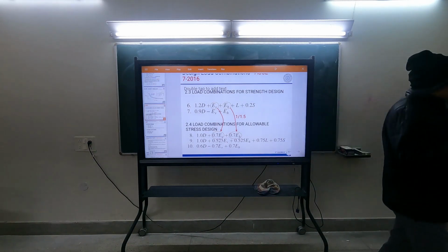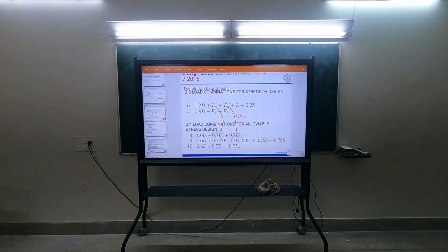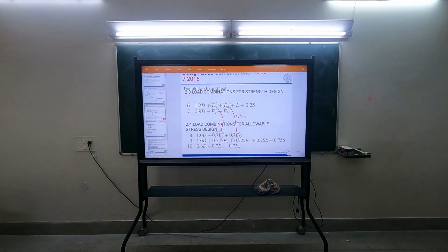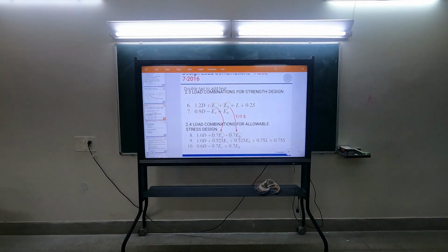Incidentally, it is by chance that the ratio between the design basis earthquake and the serviceability level earthquake also comes out to be 1.5. Or historically, that's how the DBE has been obtained. We have defined DBE as 10% in 50 years. We could have defined 8% in 50 years or 11% in 50 years. Why this came?